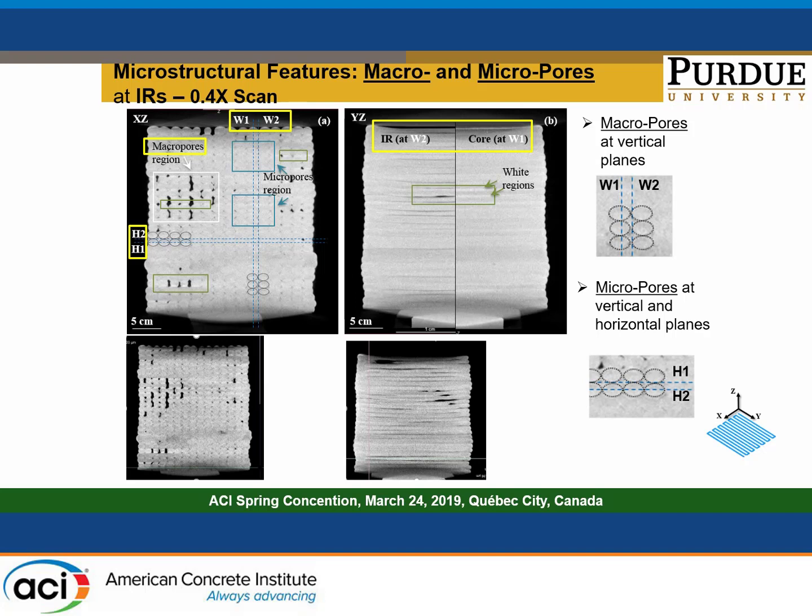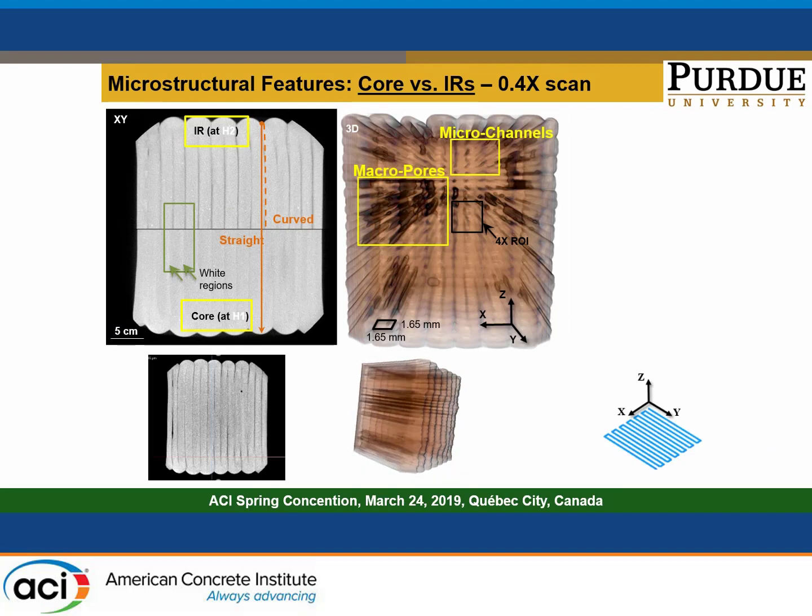Because of some fluidity-related issues, you may have some shearing of material in various layers that will result in the core of the filament having different densities and different porosities than the regions near the interfaces. There was also, at least in our experience, quite a bit of unreacted cement particles at the interfaces. This is related to different levels of evaporation that happen at those locations.